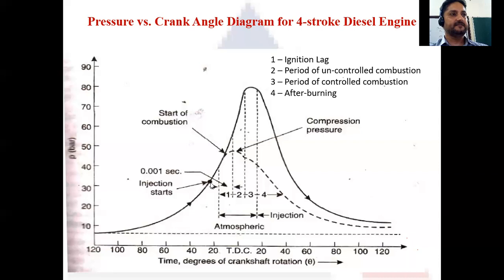As the fuel starts to enter the combustion chamber, again the phenomenon of physical and chemical delay kicks in, where the first nucleus is developed and the flame front is developed. This time lag, or time advance, in the case of a diesel engine is around 0.001 second. Now the combustion inside the four-stroke diesel engine is divided into 4 stages.